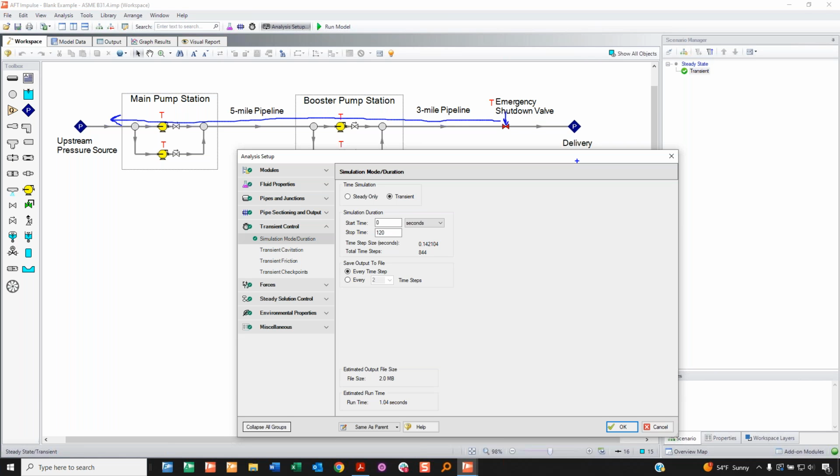Well, the speed the wave will travel at through the pipeline, which is a function of the fluid, its density, the pipe, the material, and all that. But it's effectively, how quickly does a sound wave move upwards? So in this case, the communication time, which is there and back, is 30 seconds-ish. I think it's more around 25 seconds or so. But anyway, we need a long enough simulation time to capture that moving through.